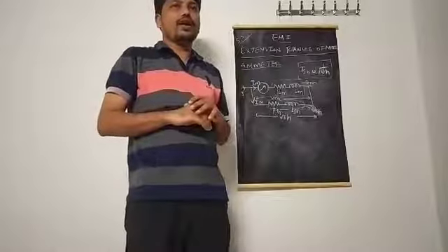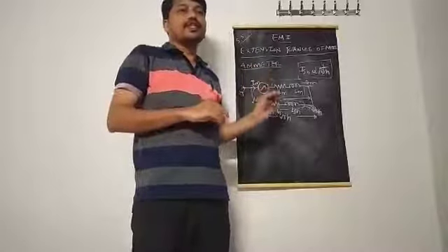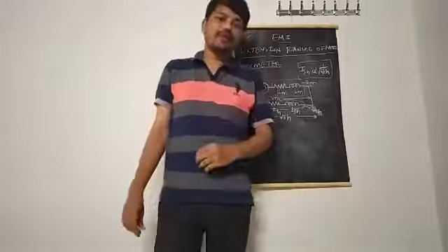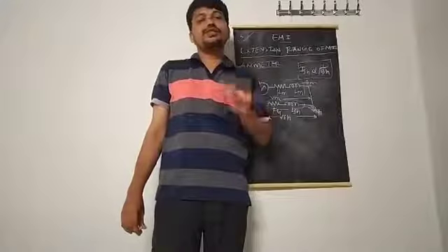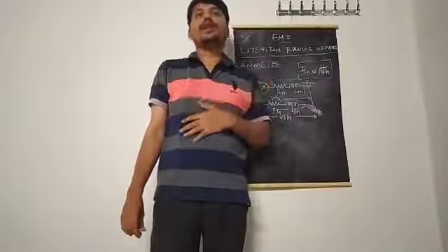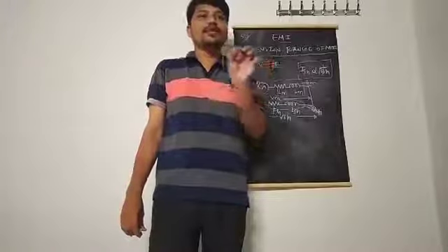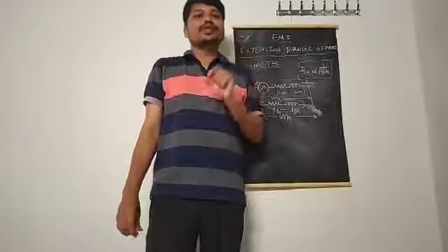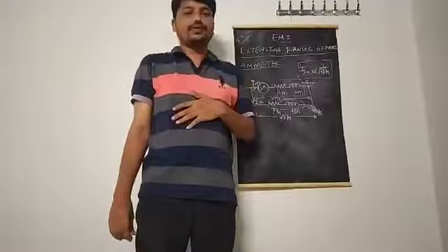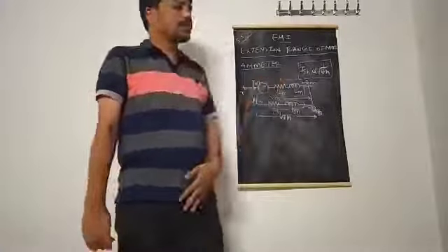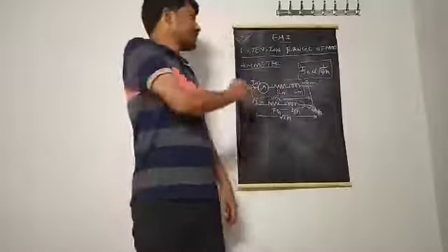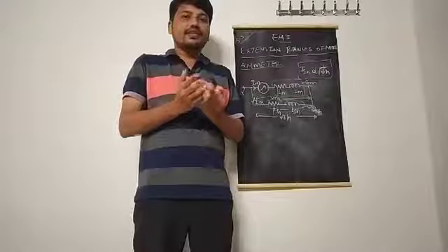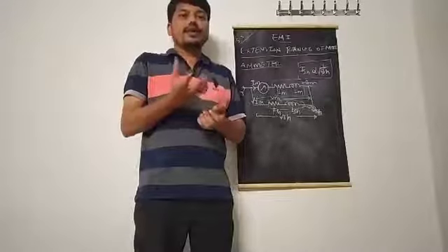Extension range of moving iron, same as how we did it in PMMC, we will do here also. There, in the permanent magnet moving coil instrument, we made a shunt connection and a series connection to extend the ammeter and the voltmeter. That is, PMMC with shunt connection is the ammeter extension, and PMMC with series connection is the voltage range extension. Here also, similar to that, we can extend the existing moving iron instrument. That means we are directly increasing the range of the instrument.